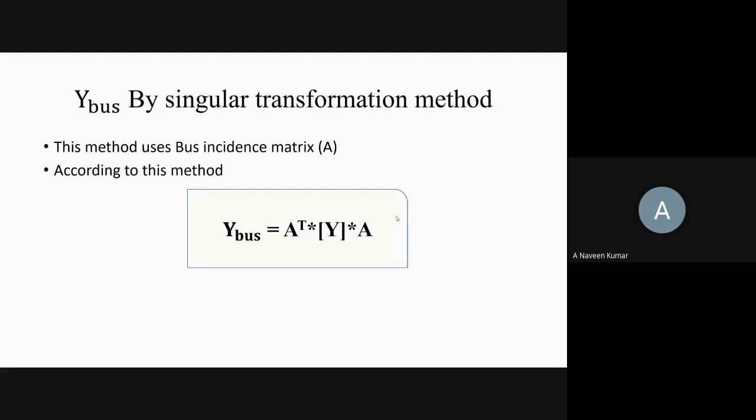But if the number of nodes is more, then definitely more equations will be involved, so it becomes very difficult to write the Y bus matrix. Then we need to go for another method, which is called Y bus forming by using the singular transformation method.